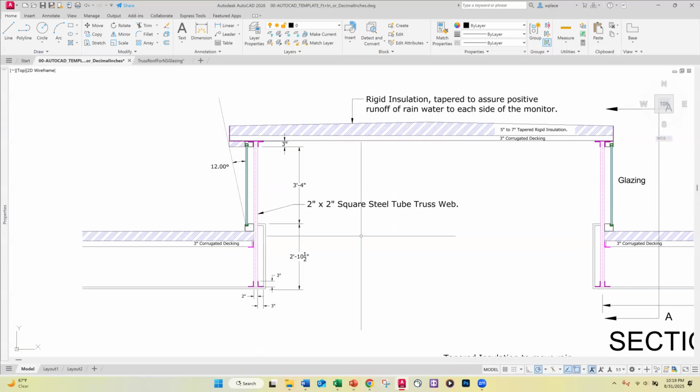You'll draw it up, and the engineer will then look at all your dimensions and understand what it is you're trying to do. And your engineer will go back and do the structural analysis on these trusses. And your engineer will either say, for your particular design, where you're spanning 120 feet, that 5 by 5 tube makes sense, or your engineer might come back and say, we really ought to go with some larger dimension like 6 inch by 6 inch. Chances are the 5 by 5 will work.